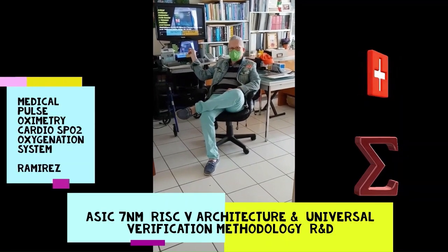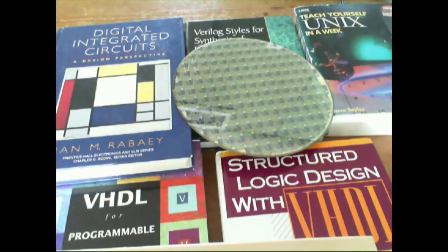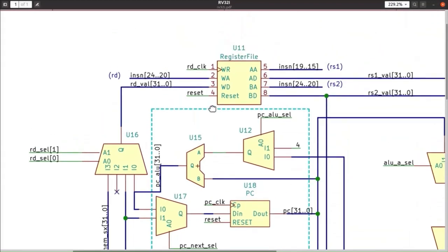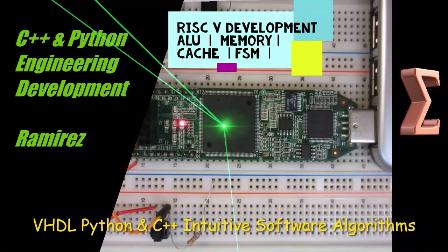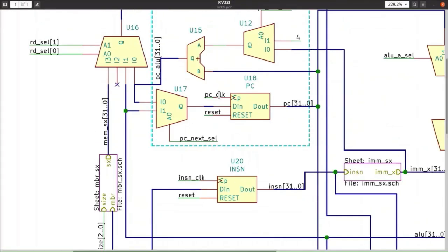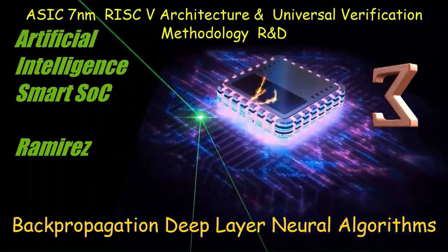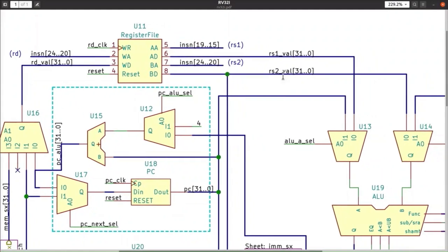The product files, in addition to the RTL in Verilog and VHDL, must include the synthesis and installation scripts. We include the reference library so that we can synthesize the design and verify that the installation was completed successfully. In addition, providing the reference library, scripts, and verification environment allows us to create this true environment.